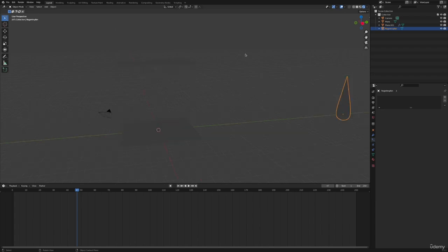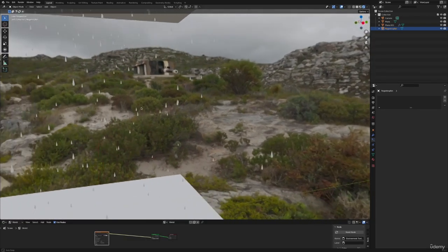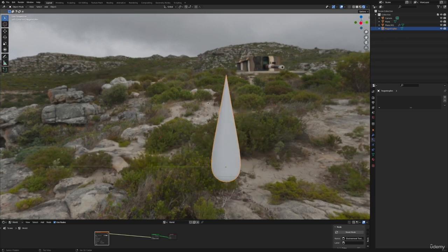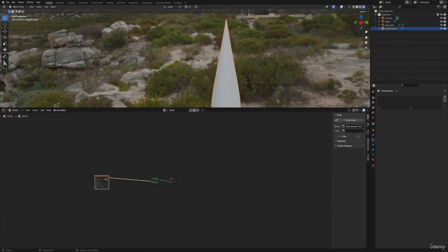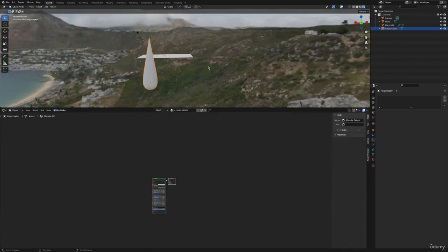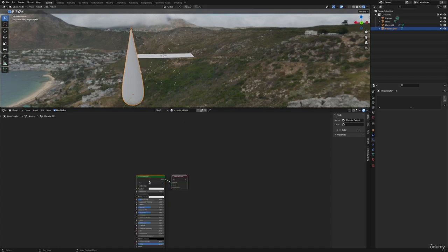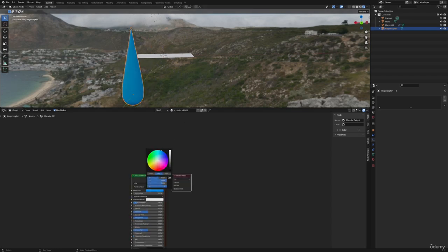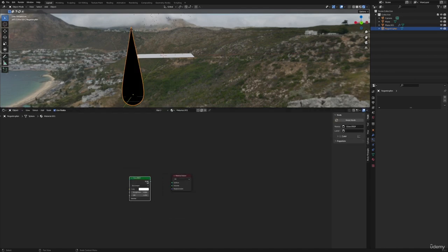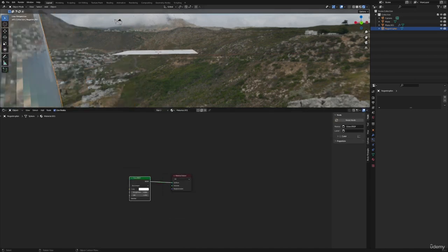And you can now see that if I scale it up and down, the drops get bigger and smaller as well. Now, if I, for example, want to make this look like a raindrop more with a glass material, then I go into the shader editor and the instance object here as well. That means I click new, and then you can look at the whole thing like this, and then we can see how everything updates. Even if I enter any color here now, you can see that this also updates in the particles. This means that we can now simply pack a glass BSDF into the surface output, and then we have our rain material right here.